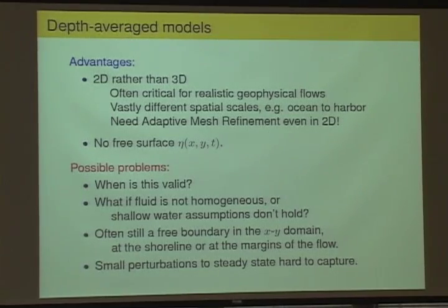Instead, we just use rectangular grid patches, but each grid cell could be either wet or dry. So the boundary is simply where the interface is between wet cells and dry cells. If you really zoom in, the boundary always looks like a stair-step pattern, but if you've resolved well enough, then that's a pretty good approximation of where the edge of the fluid is.